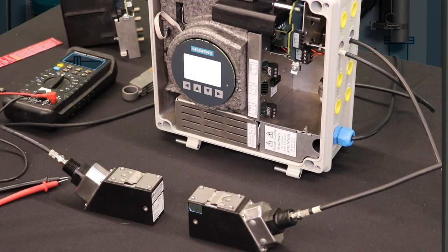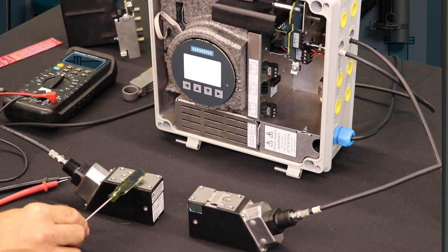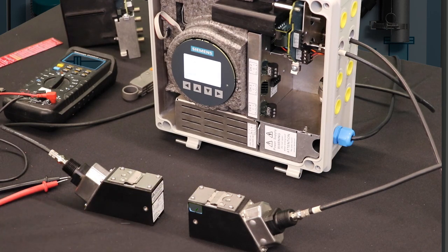And another possibility for liquid measurements only, if the sensors happen to be mounted on the pipe and reflect, what you can use is the half pipe diameter, program that in and switch to direct mount. And you can also check for the received signal.